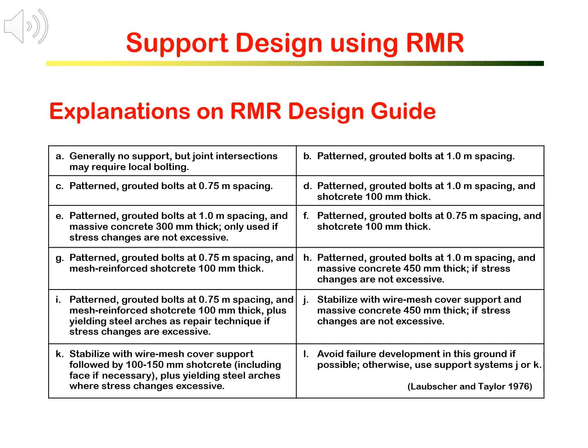L type, being the worst case, is applied in very poor rock mass. The stand-up time is extremely short. Therefore, it is important to avoid failure development by installing support quickly and immediately after excavation.